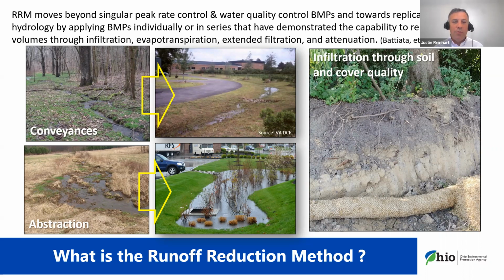So how can we convey water in the sheet flow to shallow concentrated flow to open channel runoff model that we all have learned and utilized through various runoff hydrology calculations and models on every project? How do we take our conveyances and truly mimic that hydrologic model?